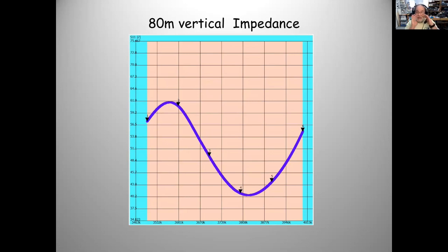I added a, what? What do we call that thing at the base? Loading coil. I added a loading coil and also a matching coil. So the combination of the two I played with, just trial and error. In about 2 hours on a hot, sweaty day, I got this thing to just tune right up on 80 meters. I thought, oh, so cool. And I learned about matching coils and loading coils.